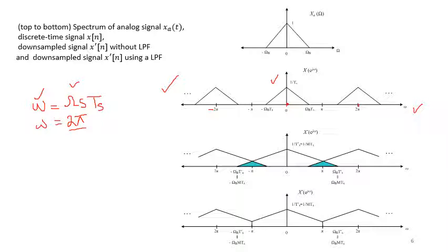sample this signal, downsample this signal by a factor of m, right? So in that case we further have scaling, that is, originally it was 1 by ts, now it will become 1 by m ts, as from the discussion on the mathematical description of what happens mathematically.